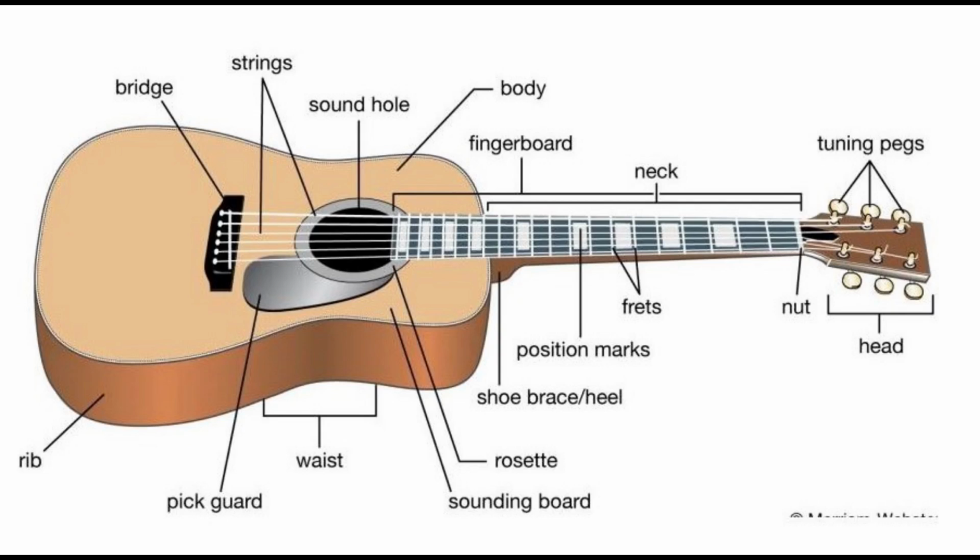The 12th fret divides the scale length exactly into two halves, and the 24th fret position divides one of those halves in half again. The ratio of the spacing of two consecutive frets is the 12th root of 2. In practice, luthiers determine fret positions using the constant 17.817, an approximation to 1/(1-1/2^(1/12)).